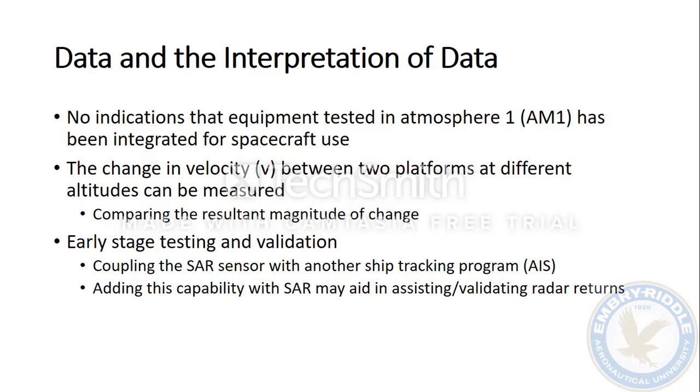So going back to the altitude, you want to talk about terrestrial versus space. So atmosphere 1 is as close to that 14.7 psia, 101.325 kilopascals at 1 atmosphere versus atmosphere 0, which is where you really want to test it. And it's mentioned in TRL maturity of a sensor or a program or something that's going from terrestrial to space based off of the 5 to 6 level. It has to be relevant environment. So something like that is definitely worth mentioning.